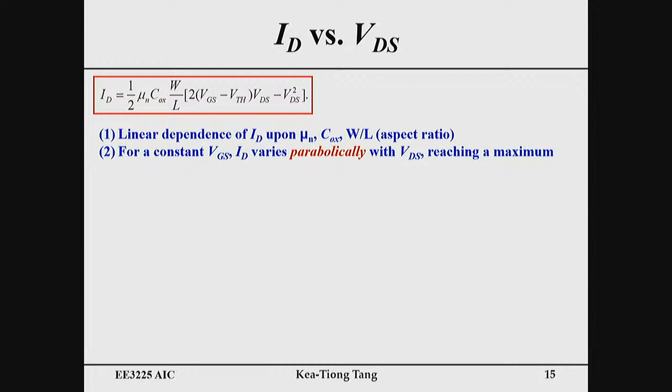It only depends on the material. For the gate oxide, it's just depending on the property of the silicon dioxide. So you have nothing to do with this. And the oxide thickness, T oxide, is another parameter that you have no control. Okay? The foundry actually decide how thick this parameter is. Okay, so this is C oxide.